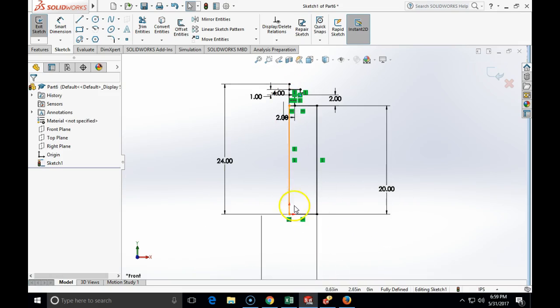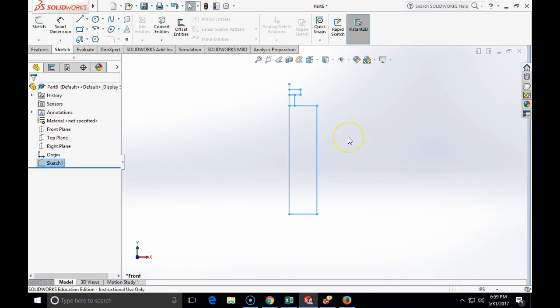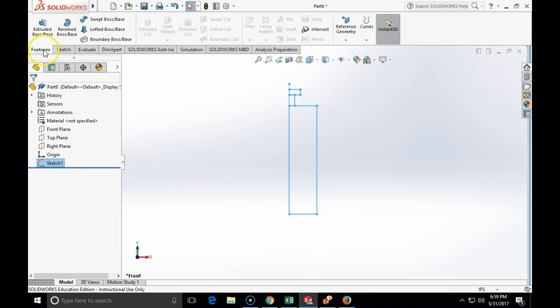Do you see a bottle now? Like kind of a width of half of the bottle. Going to close this sketch. Sketch is fully defined. Now, because I used those diameter relationships and I used the center line, it will kind of prefer revolution. So let's see what we have as options: extrude and revolve boss. So let's click on revolve boss.